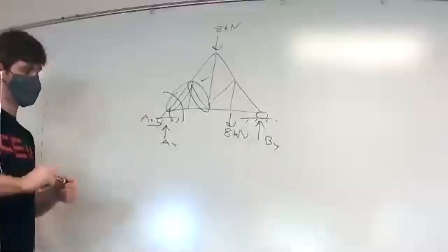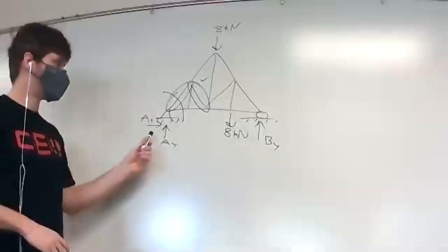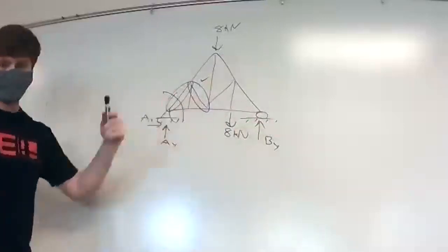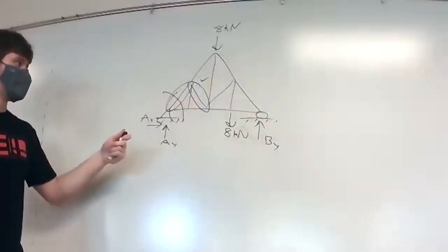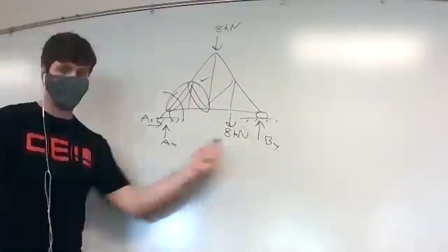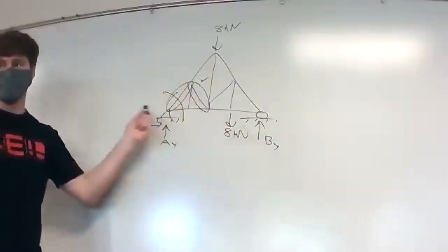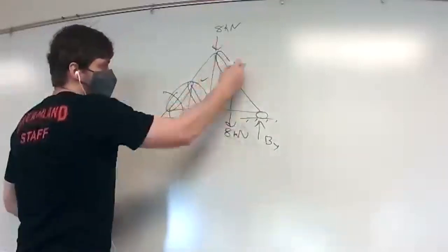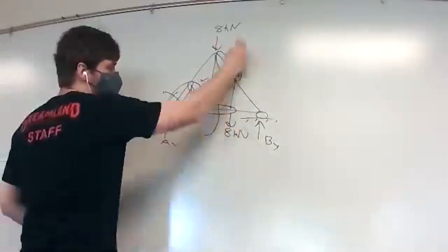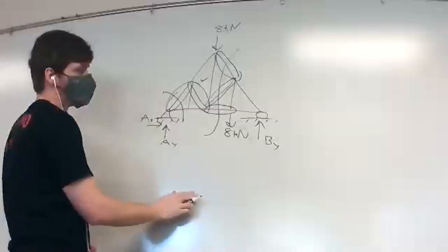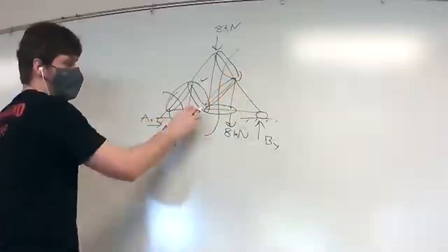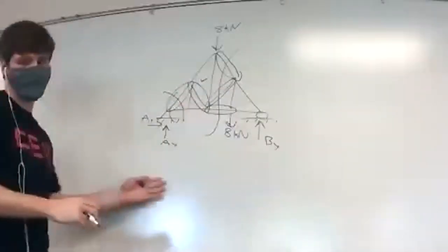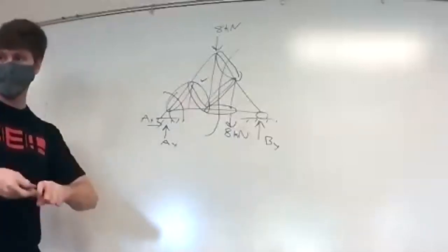And internal forces for truss problems like this is just that method that I explained. You identify if you have any zero force members. We quickly found this one. And then if you're asked to find something that's not zero force, find your reactions, start taking cuts where you have a member you're trying to solve for. We had one here, so we did a cut like that. This member and this member are unknowns, and then those are your answers.